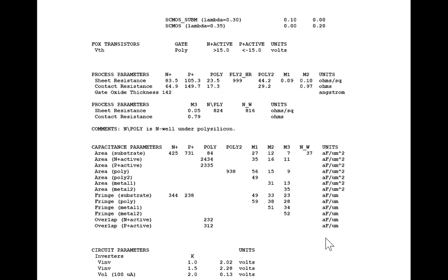The model we built for the transistor using the capacitor is not entirely accurate. Oh yeah, it's not real accurate yet. We're going to improve on it later, but we can still use that for the rise and fall times. We're going to come back later and do a better job of calculating what COX is, and do a better job of calculating capacitance. It's not far off for a minimum-sized device in a 0.5 micron process.